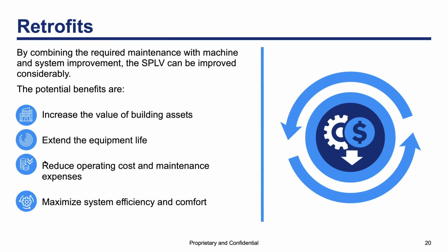The second point to consider is component sequencing and stability, whether it's staging or controlling chillers with a VFD, or controlling the fans in cooling towers. Regardless of the case, proper sequencing is part of optimization. For example, one chiller can operate at 100% capacity or full speed if the chiller has a VFD, but two units can share the load at 50% capacity or 50% speed. Now, this is valid if and only if the system is designed to accept these operating conditions. Not always are two chillers at partial load more beneficial than one chiller at 100%.